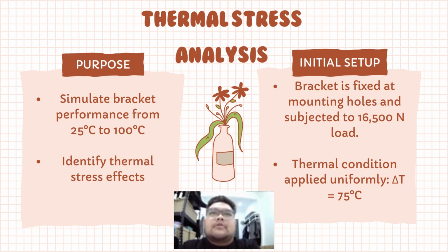I will be presenting about this thermal stress analysis. The purpose of thermal stress analysis is to simulate bracket performance from 25 degrees Celsius to 100 degrees Celsius. The second purpose is to identify the thermal stress effect. The initial setup is that the bracket is fixed at the mounting hole and subjected to 16,500 Newton of load, and then the thermal condition is applied uniformly. The temperature difference is 75 degrees Celsius.